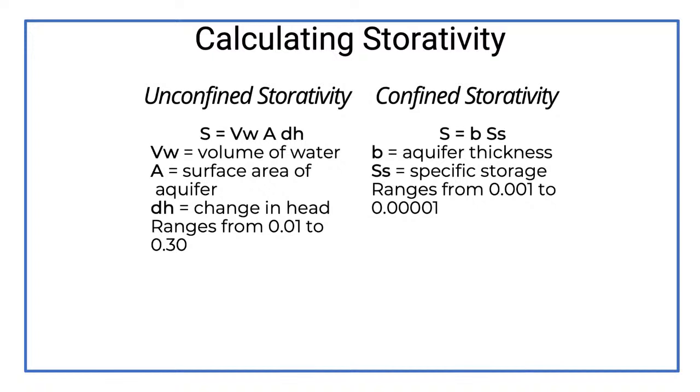In a confined aquifer, the water storage is supported by an intricate network of grains that fit together, and when you start dewatering these confined aquifers so they're not saturated anymore, you start to collapse that structure down. You never get that back. You can pump water down there all you want, but if you've collapsed that structure and you get the subsidence, now you've lost that storage capacity forever.